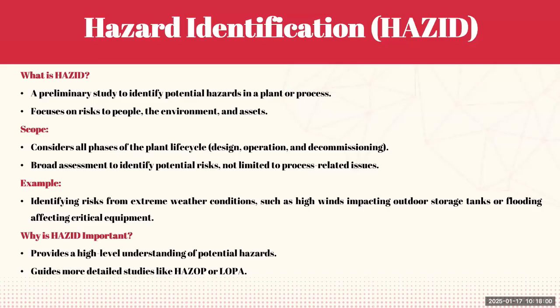So the scope of a HAZID, it covers all phases of the plant life cycle: design, operation, and even decommissioning. Unlike more specific studies, it takes a broad view, addressing risks that aren't solely process related. For instance, it considers risks from extreme weather conditions, such as high winds that could destabilize the outdoor storage tanks, for example, or flooding that might disrupt operations.